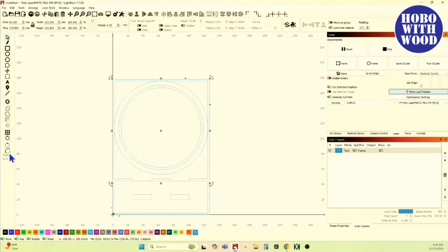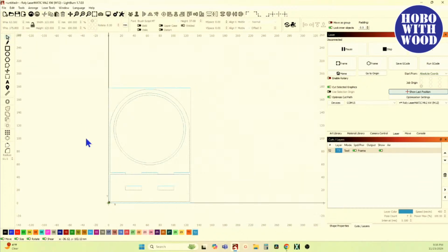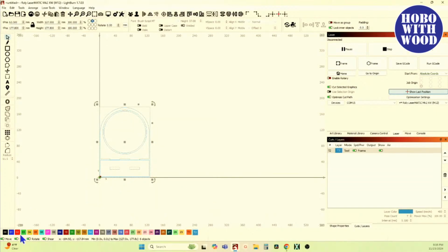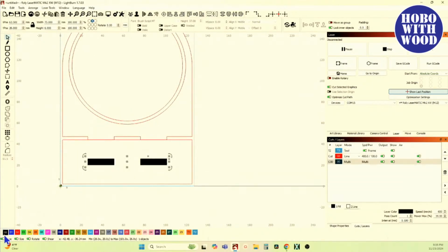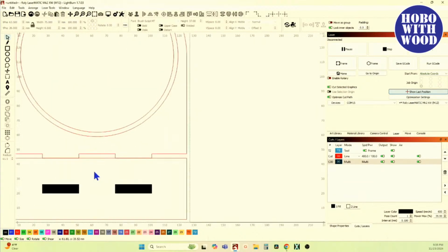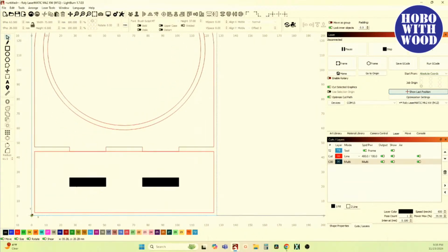Now I've got that. Go to my radius tool. It's a 61.5 radius there and there. Oops, didn't get it there. Go back to your selector tool, select that beginning toolpath, and now that's going to go, not that or that. Those are on the red path, and I'm putting these on the black path. Now, I've got 2 tabs, and I've got these set up as engravings, not as cutouts.